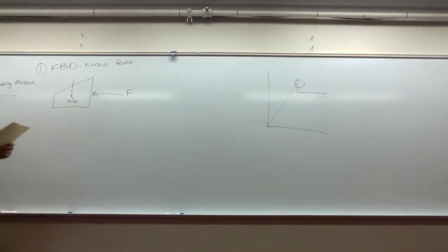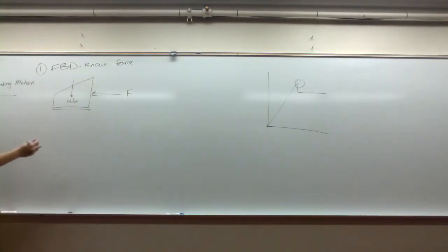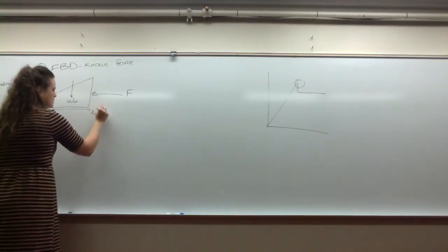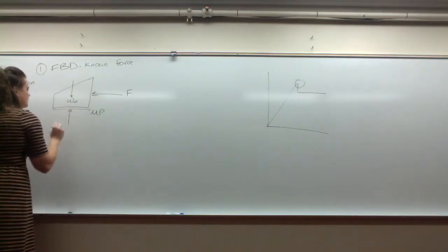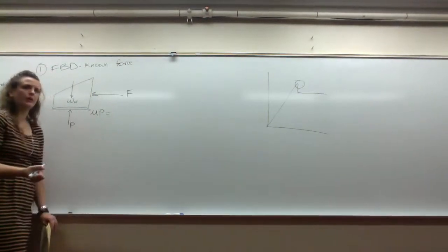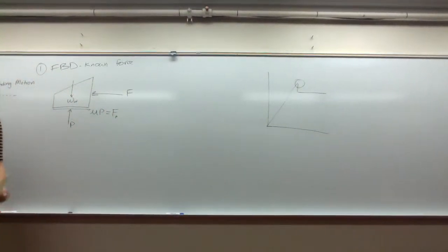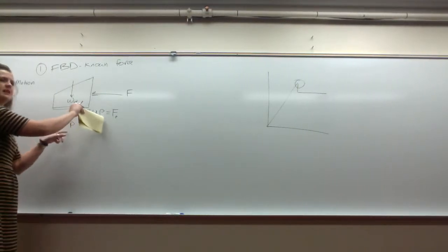Opposite of the motion, okay? So we have a friction force acting between the wedge and the ground. I will call that mu p, and a normal force from the weight of the wedge and the ground that I will call p. This mu p is Coulomb friction, my friction force at p. Fp and p are not two different unknowns because they share the same normal force.